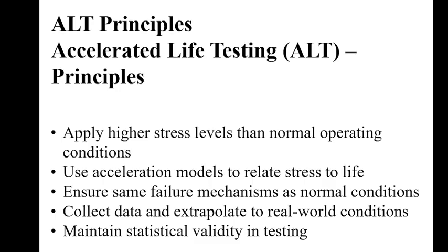The core principle of accelerated life testing revolves around increasing stress levels to induce failures more quickly while still maintaining realistic results. In ALT, you can apply higher levels of stress such as temperature, voltage, or mechanical load than those typically experienced in normal operations, and we can see whether the system can operate continuously under this stress or not.